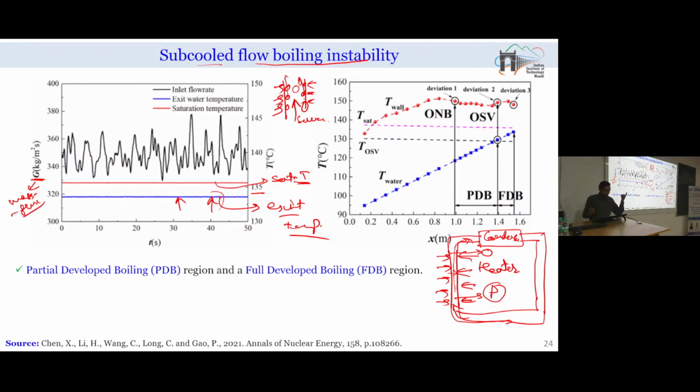Now, as I told you, we will not have a constant value of the flow rate, we will have an oscillatory flow rate. So, here you can see this mass flux is of oscillatory nature, it is not fixed. So, if I have to apply this in any practical scenario, I need to design the system in such a way that the amplitude of these oscillations is as low as possible, and I should be able to get some unique average value of the flow rate during the entire period.